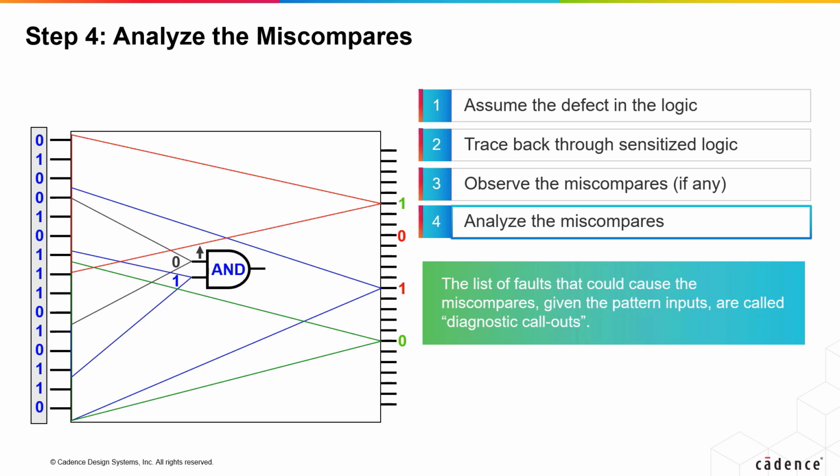The actual algorithms are much more sophisticated than this, and can handle multiple simultaneous defects, use multiple failing patterns, and so on. Specifically, if you assume that there could be multiple defects, then all of the faults in any failing cone must be considered, not just the overlaps of the cones. The list of possible faults is prioritized, using fault simulation of the candidates. But this should give you an idea of how the process might be performed.